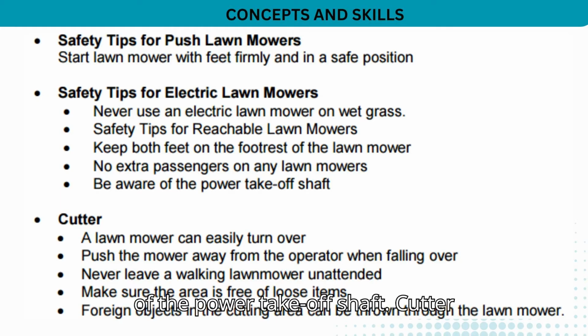Be aware of the power take-off shaft and cutter. A lawn mower can easily turn over. Push the mower away from the operator when falling over. Never leave a walking lawn mower unattended. Make sure the area is free of loose items. Foreign objects in the cutting area can be thrown out by the lawn mower.